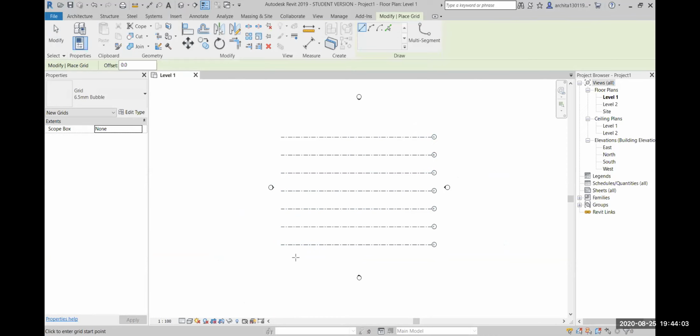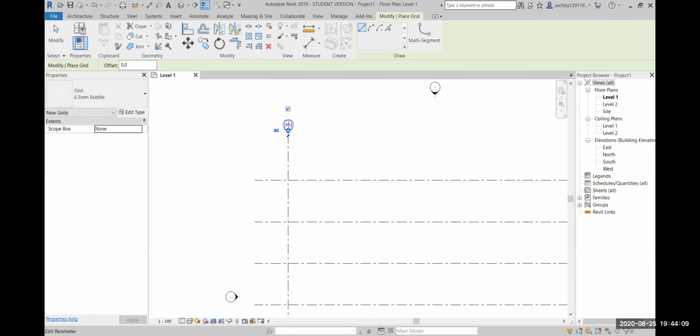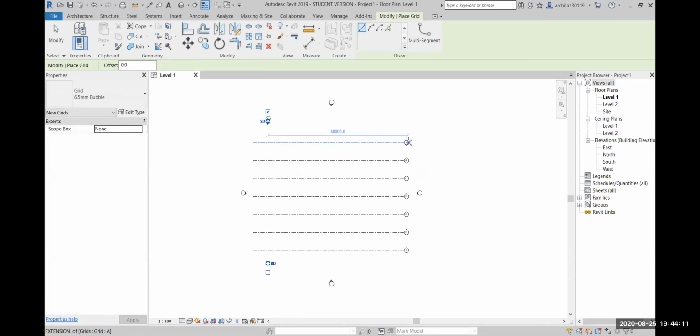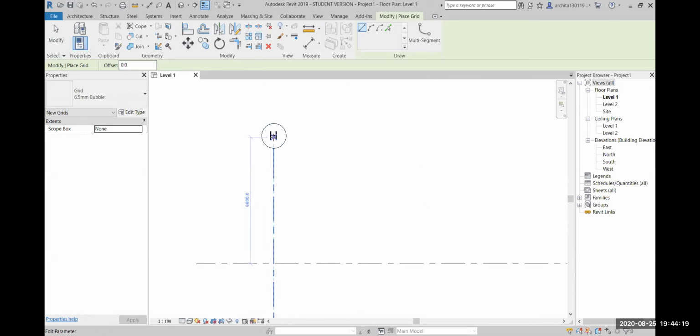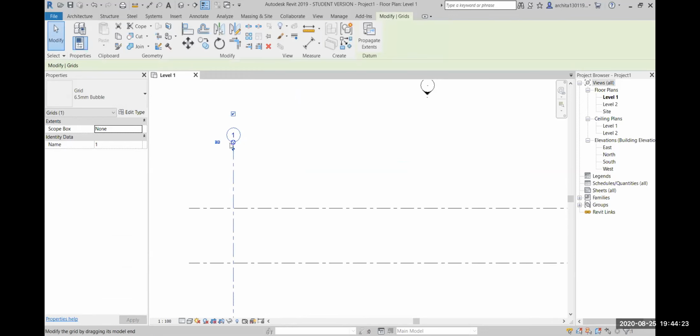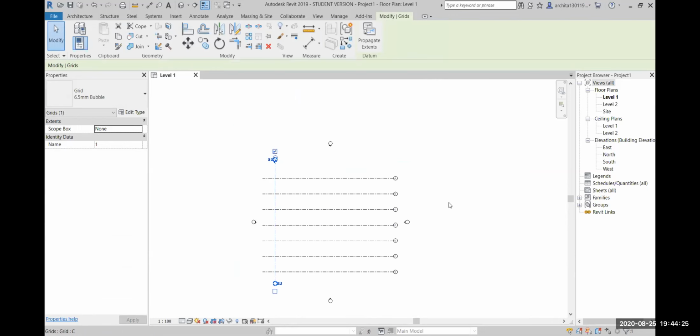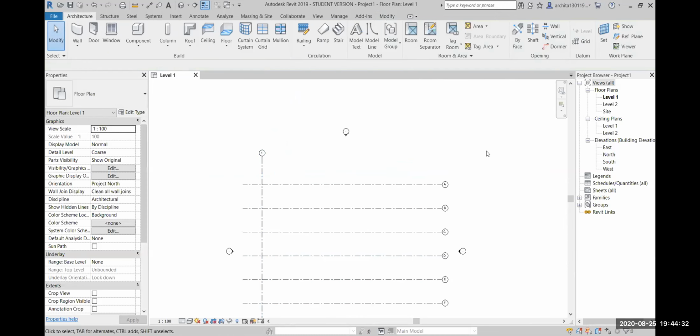So now you have this vertical grid. When you copy this and go to the vertical one, it will follow the same series A, B, C, D, E, F, G, then start with H. But I want the horizontal grids to be in alphabetical order and the vertical ones in numerical order.